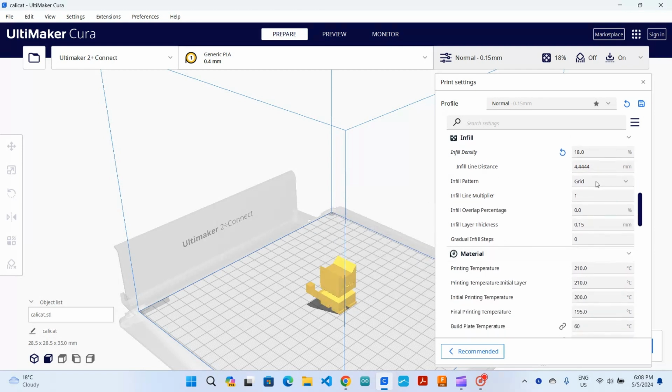And the next important thing is the infill patterns. There are really a bunch, and for cosmetic stuff, again, it doesn't really matter, but for some things, you do want to choose a specific infill pattern. For really strong stuff, I would suggest cubic, but you can look through these on your own and just slice it and look at the preview and see what that looks like.